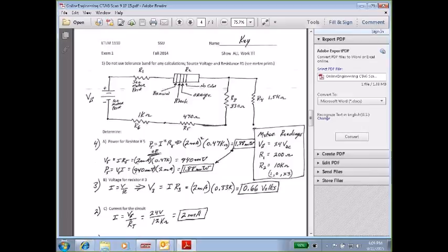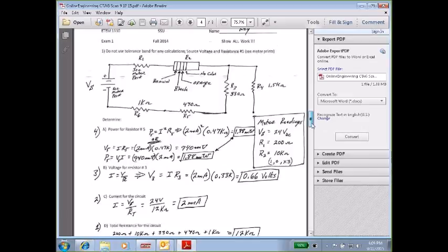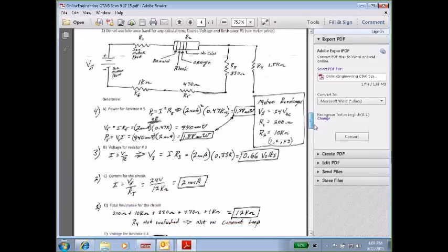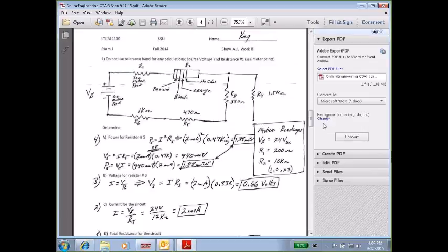We also have the use of meters on this exam, and we have the resistor color code on this exam. But let's just look at this first question. We have a circuit here, and there's a lot of concepts covered with just this one question. It's obviously a series circuit. That brings up the three laws for a series circuit. First of all, to find the total resistance, you take the sum of the individual resistors around the closed loop.